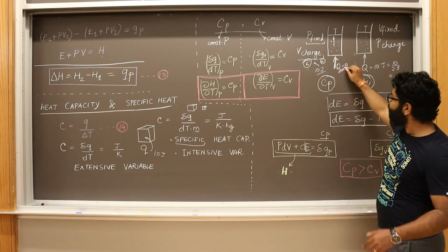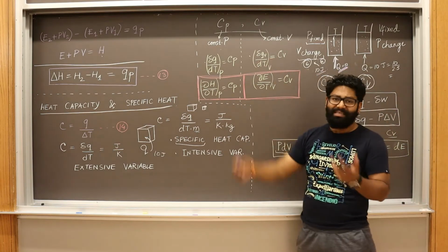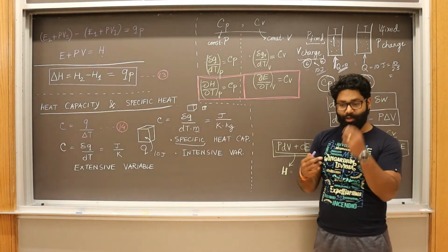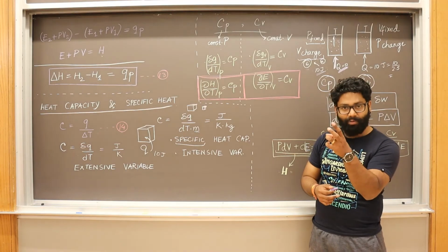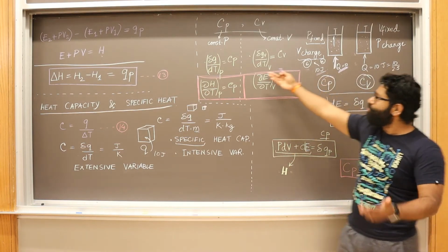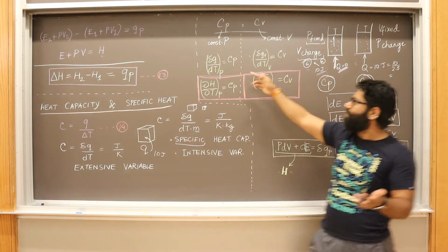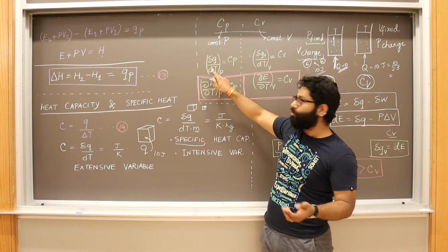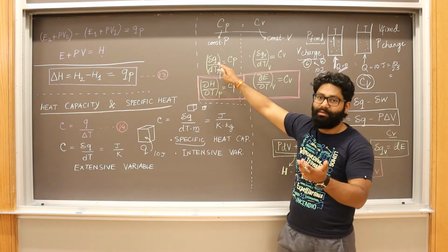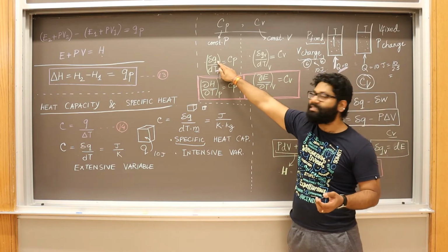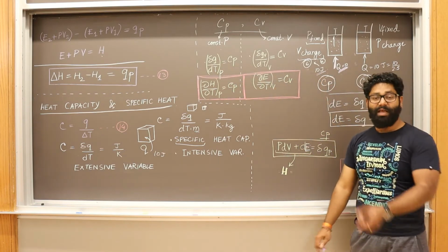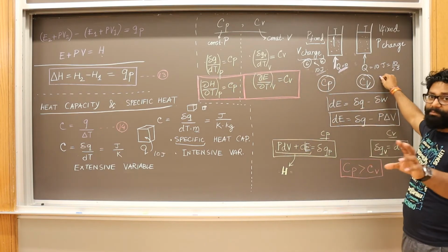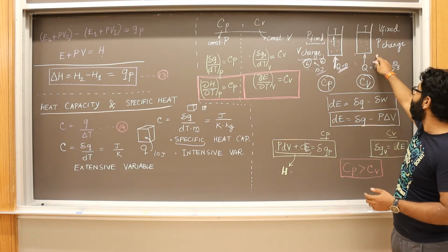If you are giving more Q, then inherently Cp is increasing, right? If you are giving more heat to raise the temperature by that amount, then inherently you are increasing the Cp, because what is Cp? It's dQ by dT. To raise the same temperature, you are giving more, because more heat is needed, since some of it is going to waste. Now, the story becomes different when you have the volume fixed.